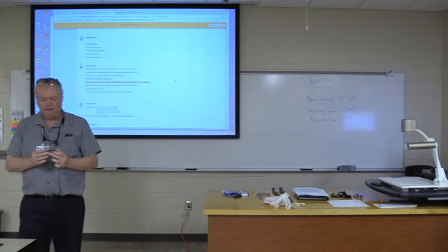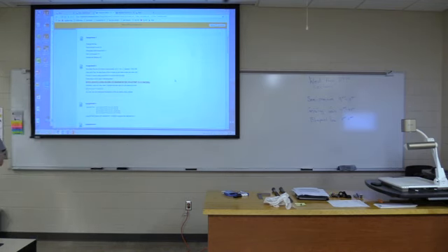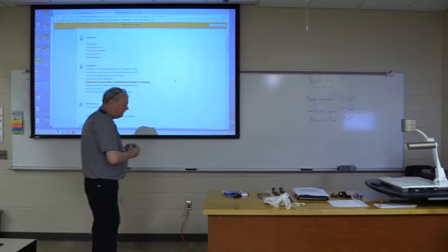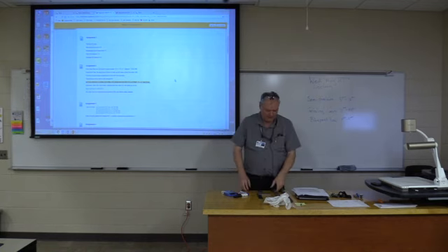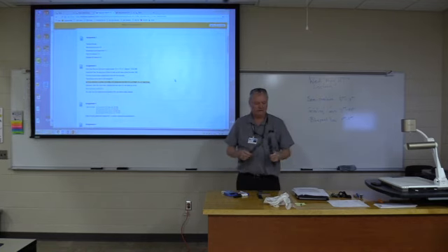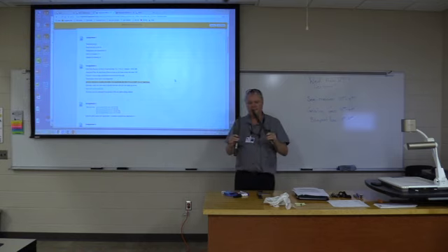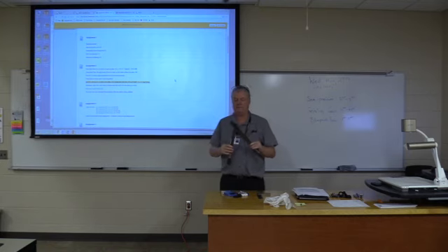Okay? And then if you look at the assignment, you're going to cut yourself 2 pieces. So in the bandsaw demo, it shows you how to set that, set your piece, measure your piece, cut it. And what you're going to then do, and I'm going to bring up a PowerPoint in a few minutes, is use whatever files you deem appropriate, hand files. So this larger one is a coarse, double-sided. This one is a finer, single-sided, single cut.